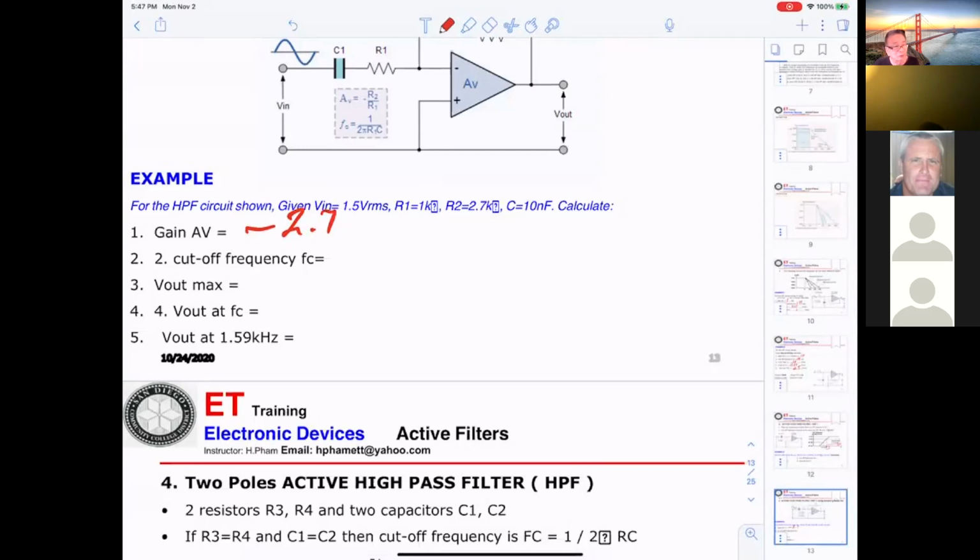Try to make sure you go to the op amp. You get inverting and non-inverting. When you see the circuitry, you have to tell me which one. Input applied to the negative will be inverting. Input applied to the positive means non-inverting. That is the first thing you must know.